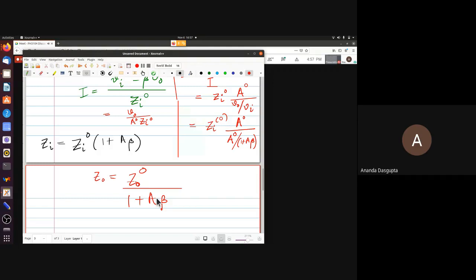So negative feedback actually makes the circuit behave a lot better as a voltage to voltage amplifier than it would otherwise. It does cut down the gain, but makes the gain more stable and makes the input impedance go up, makes the output impedance go down. Those are things which you would want. In fact, there are other things which I will not talk about now because it will not make much sense unless you see the video that's coming up, which is about frequency response.